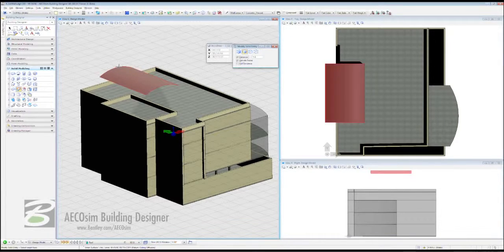With that, we're going to select our curved surface. It goes hatched, select it second time to make it locked in, and then just click once again off, and you will see it thicken by 1 foot. Now we need to get the walls in.